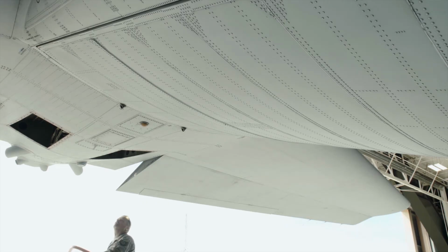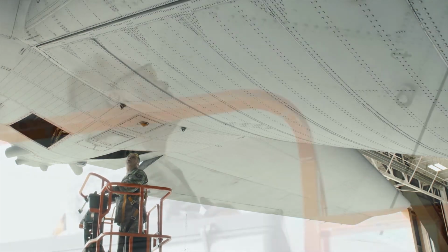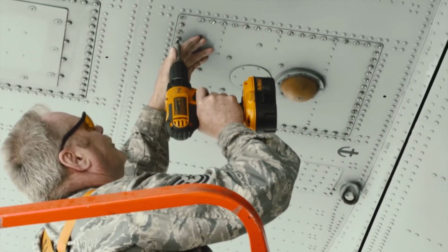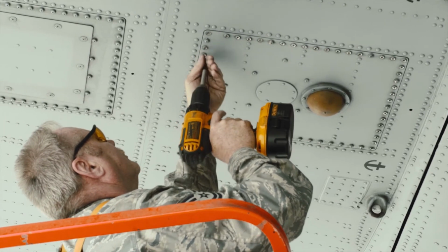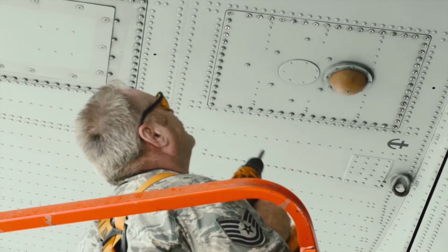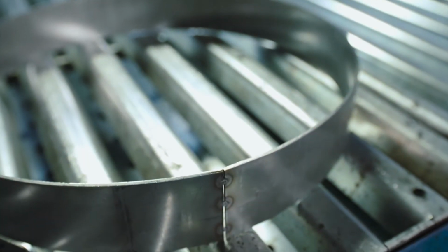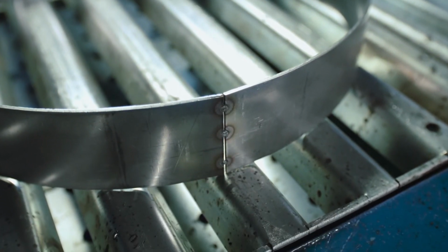Fasteners are found in almost every area on aircraft and equipment and are often problem areas. These areas are subject to heavy operational loads, moisture intrusion, and possible corrosion from the surrounding substrate skin. Spot welded assemblies are highly susceptible to corrosion because of water entrapment caused by holes and gaps created between the parts.